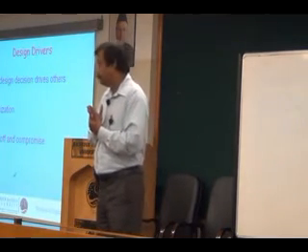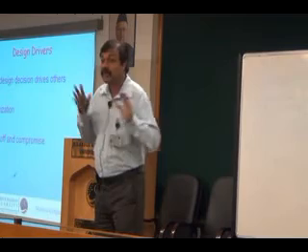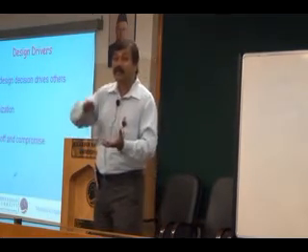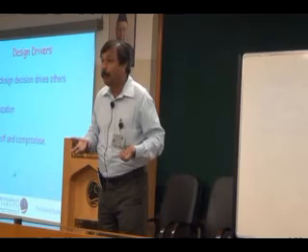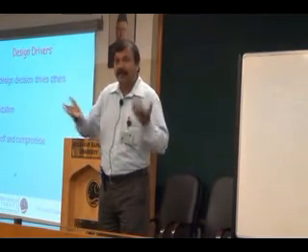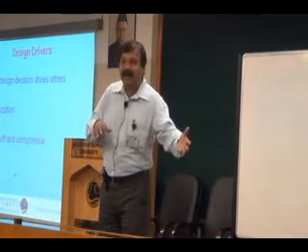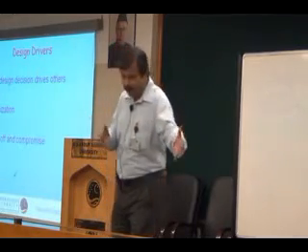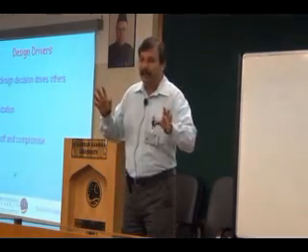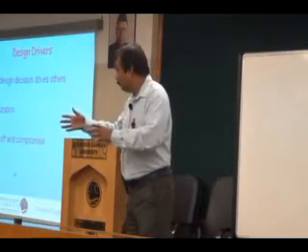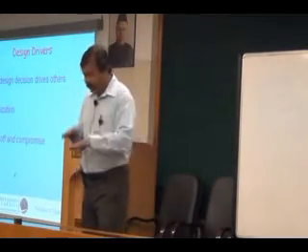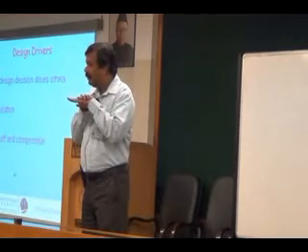At the same time, the stability is low. You can see accidents in which the whole vehicle topples. You must be knowing better. Have you ever seen an Indica toppling over? Relatively speaking, a Scorpio toppling over will be more common. Why? Because the center of gravity is high.